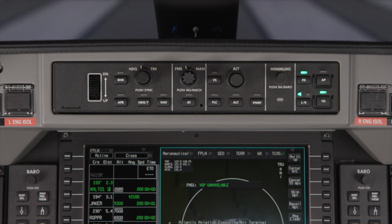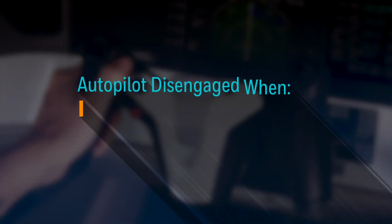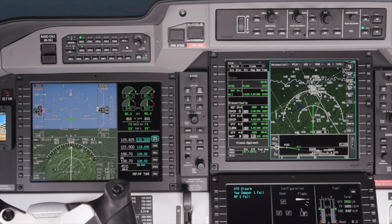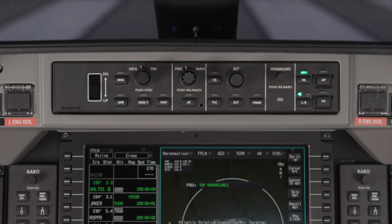The yaw damper can then be disengaged before landing by pressing the quick disconnect button or the yaw damper button. To disengage both the autopilot and the yaw damper together, push the quick disconnect button. The autopilot will also be disengaged if the yaw damper is disengaged, a trim interrupt switch is pushed, or if one of the 4 manual trim buttons is activated. The yaw damper is automatically engaged whenever the autopilot is engaged. To engage the yaw damper without the autopilot, push the yaw damper button.